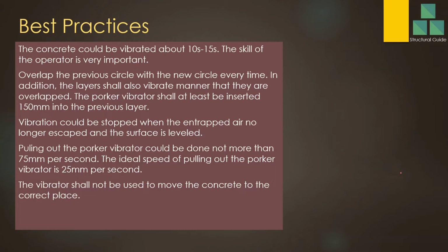The poker vibrator shall be inserted at least 150 millimeters into the other layer. Vibration can be stopped when the entrapped air is no longer in large amounts. One of the purposes of vibration is to remove the entrapped air. Knowing when that happens comes from experience and skill. When you feel it has removed almost all the entrapped air, you have to stop the vibration.